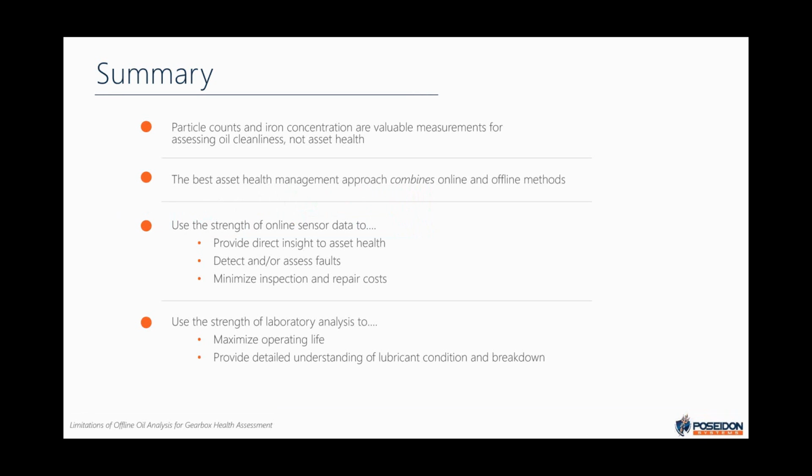Laboratory analysis is still useful though. Offline samples can provide information about the quality of the oil in the system, how the additive packages are aging, and other potential contaminants besides just wear debris. Understanding the cleanliness of your oil can lead you to maximizing your operating life overall. So by using a combination of these 2 methods, you can better understand the health of your oil, the health of your gearbox, and you can ensure that every maintenance decision is as best understood as possible before sending people out to go climb or change out gearboxes.